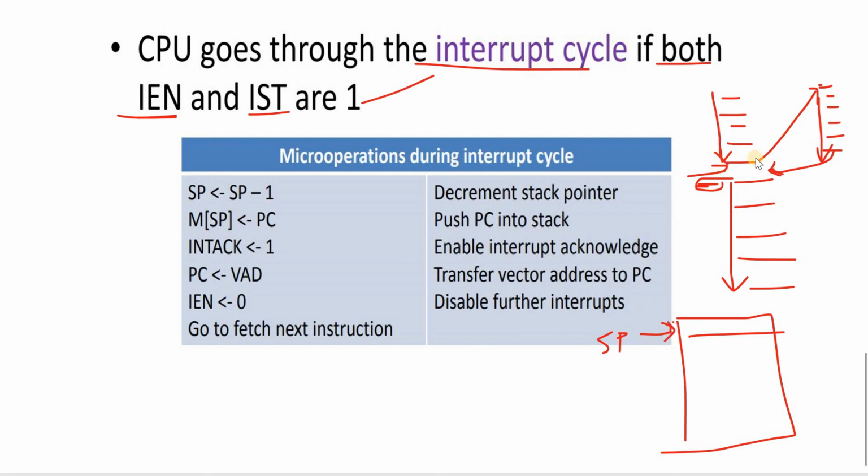So if an interrupt is received, the cursor goes to the vector address and this value is pushed into the stack, whether it is a byte or 16 bits depending on the location. The stack pointer is decremented by 1, and the address is temporarily stored inside this location at the top of the stack segment.